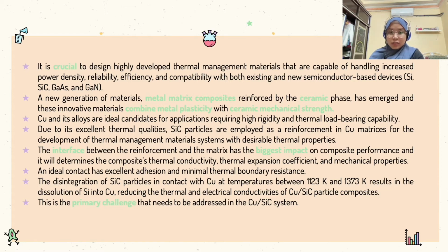The disintegration of silicon carbide particles in contact with copper at specific temperatures such as 1123 Kelvin and 1373 Kelvin will result in the dissolution of silicon into the copper. This will reduce the thermal and electrical conductivity of the composite, the copper silicon carbide composite. So, this is the primary challenge that needs to be focused on in the copper silicon carbide particle composite.